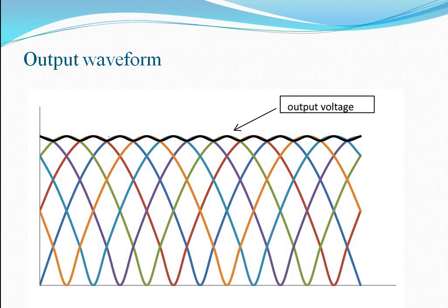One of the advantages is that the phase shift of 30 degrees is utilized to eliminate the AC side harmonic currents of order 5th and 7th, and also the DC side 6th harmonic voltage. And by adjusting the tappings on the star connected transformer, the converter DC output voltage is also controlled.